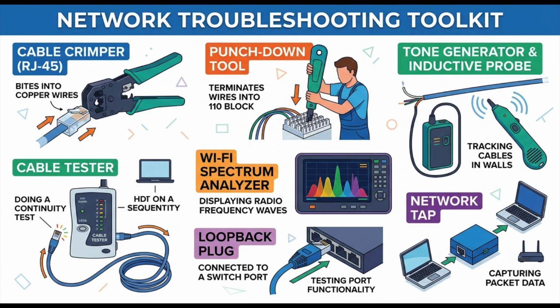Right. Picture the back wall of a telecom closet. You might have thousands of raw cables emerging from the ceiling, representing every single wall port in the entire building. That sounds overwhelming. It is. So to make managing all those connections possible, technicians terminate them into stationary plastic blocks with rows of metallic grooves. These are often called 110 blocks.